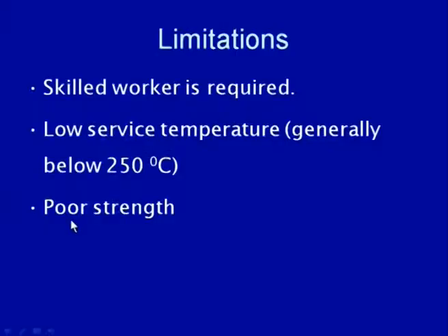Another important limitation is the poor strength of the braze weld, because these cannot take very severe mechanical load, and they will fail under conditions of high load and high temperature, and that is why these are not preferred for severe mechanical loading conditions.